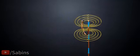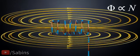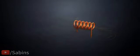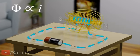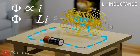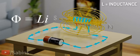Clearly, simply by increasing the number of loops, we can increase the magnetic flux. We can also increase this magnetic flux by increasing the current through the coils. A constant called inductance connects between the magnetic flux and the current's value. The value of inductance depends purely on the geometry of the coil.